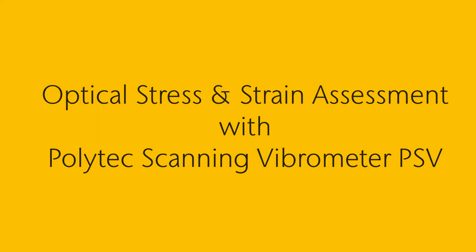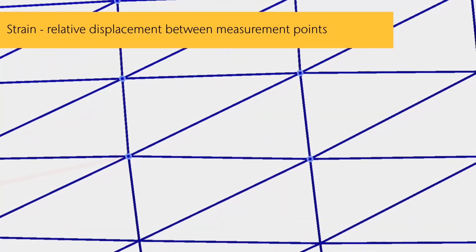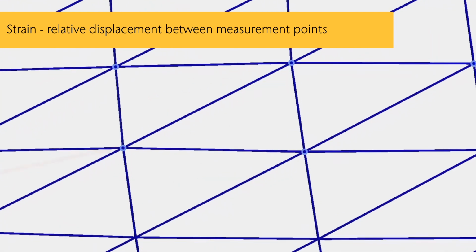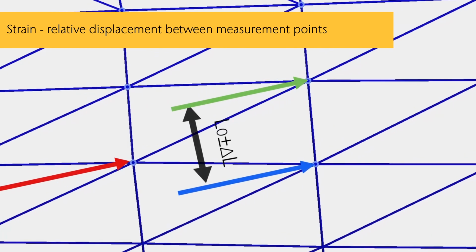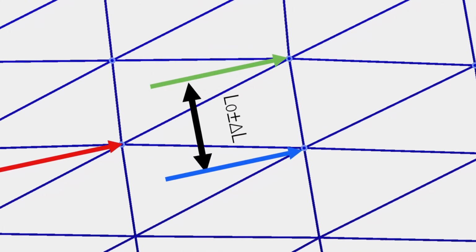The measurement of strains and the calculation of stress by means of the material parameters Young's modulus and Poisson's ratio is essential for durability predictions and thus safety relevant. Measuring the spatial distribution of strain requires assessing the relative displacements between adjoining nodal points of the surface of a sample.